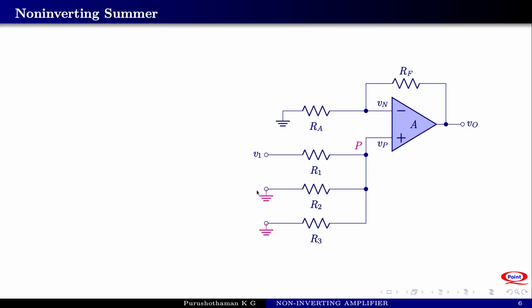So by this circuit diagram you can see that for V1, there is a current, of course. That current cannot take this path. So that current is passing through these two resistors. And you can see that R2 and R3 are in parallel. So what will be the voltage at this point? By potential divider rule, it is V1 into this value divided by the sum of resistances, R1 plus R2 parallel R3.